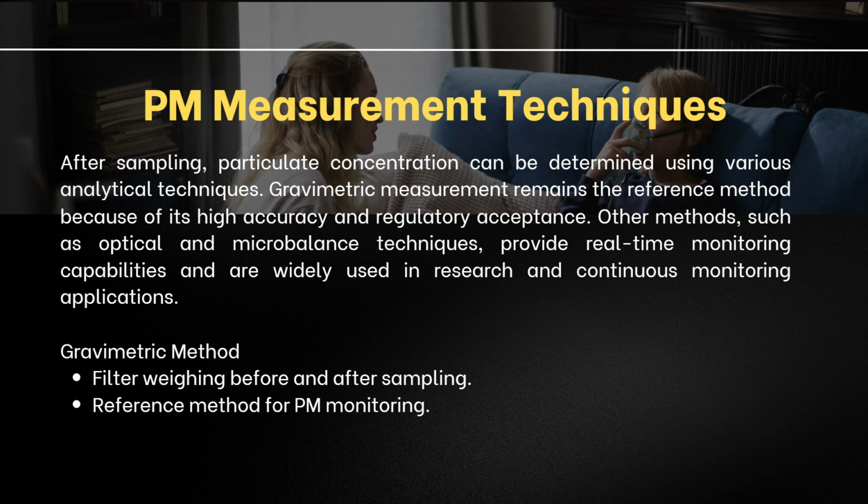For the PM measurement technique, after sampling, particle concentration can be determined using various analytical techniques. Gravimetric measurement remains the reference method because of its high accuracy and regulatory acceptance. Other methods such as optical and microbalance techniques provide real-time monitoring capabilities and are widely used in research and continuous monitoring applications. The gravimetric method includes weighing the filter before and after sampling, and is the reference method for